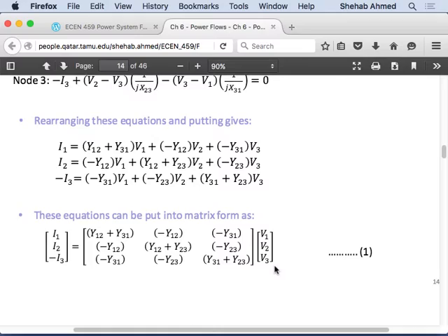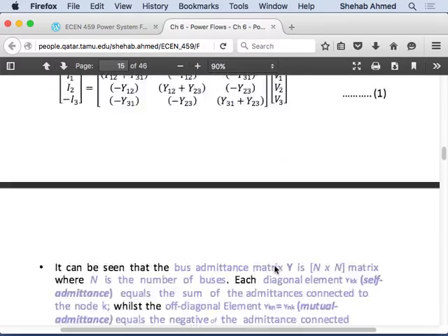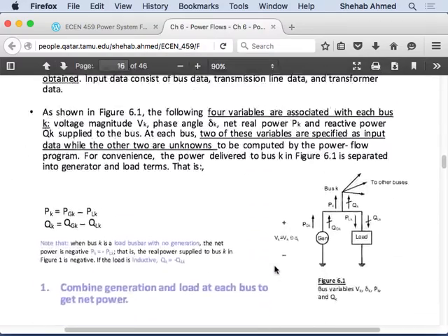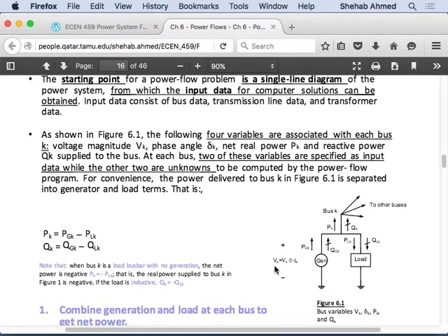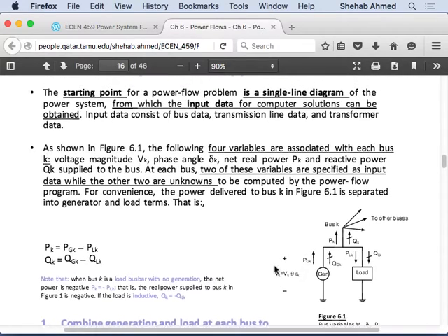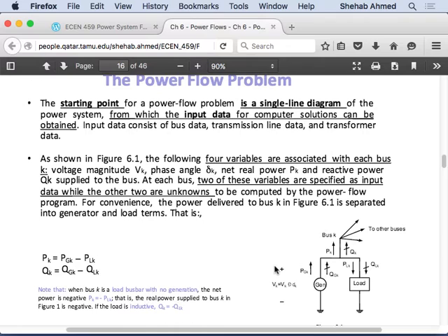We typically have a power plant, typically gas turbine based, that will be acting like this reference power plant. It will be providing fixed voltage, but fluctuating power, right? So I will know, and I will use it typically as my reference. So angles will be measured with respect to that power plant as well.